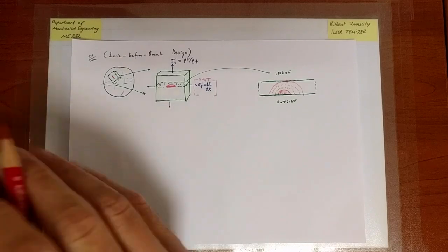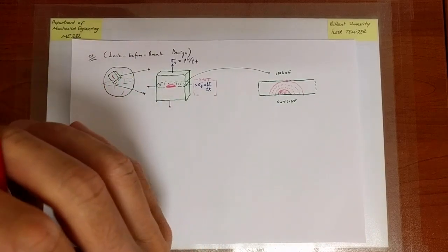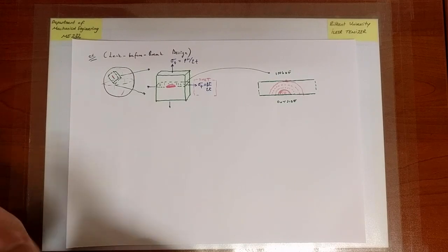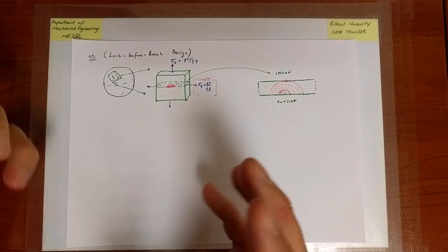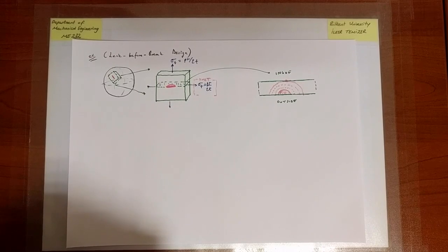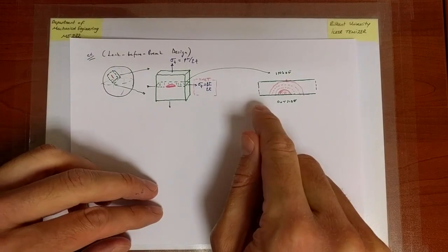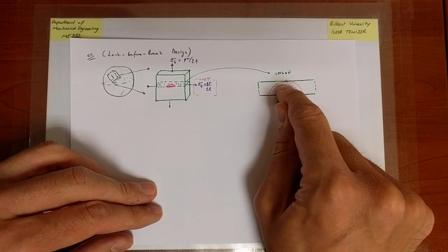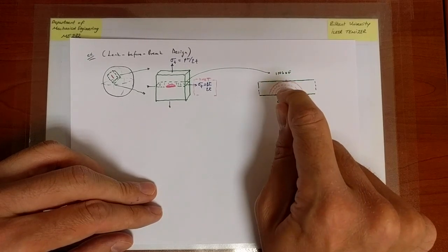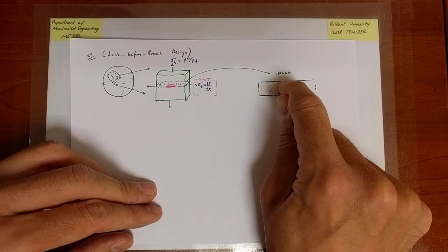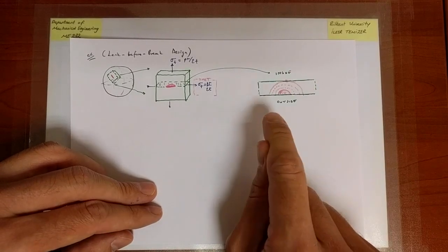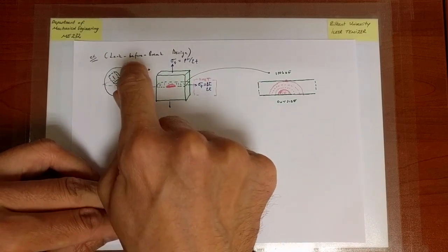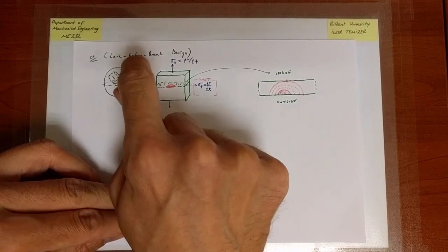Now, of course, leakage is another scenario. It's probably also not something that you desire, but leakage is something you can detect safely with sensors, whereas explosion, if it occurs, is catastrophic and sudden. So what you would like to have is a design such that if there is a crack and it will grow, the design will be such that at the point of possible leakage, fracture is not a concern. So in other words, this design should leak before break instead of break before leak.